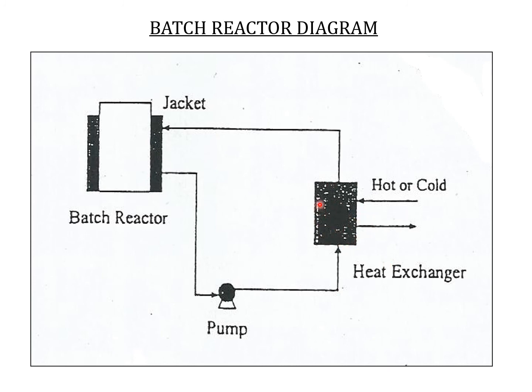I want to heat it or cool it, depending on whether it's exothermic or endothermic, whether you need the cooling or the heating. Whatever it is, it is done externally, then sent back to the jacket. This is one way of operating a batch reactor. We can have the jacket itself as the cooling, which we've seen in many cases, but sometimes people prefer to have this for batch, and maybe also continuous systems sometimes, to take it out, cool it, and send it back to the jacket.